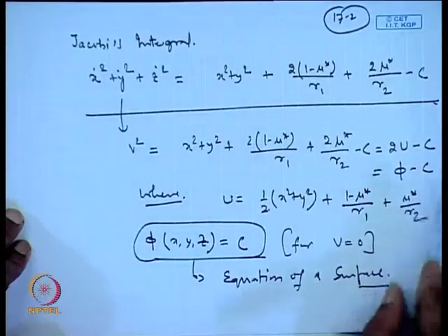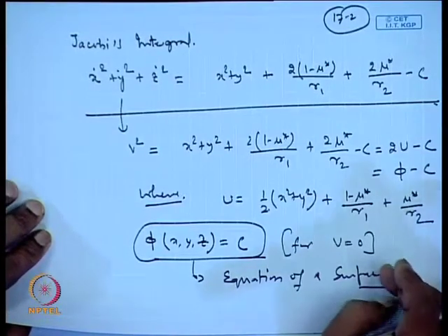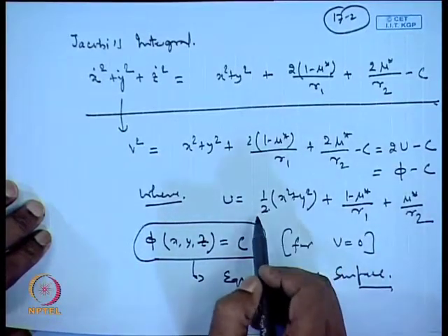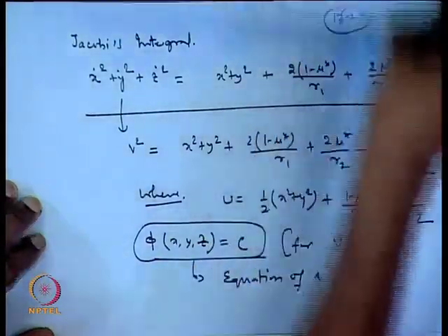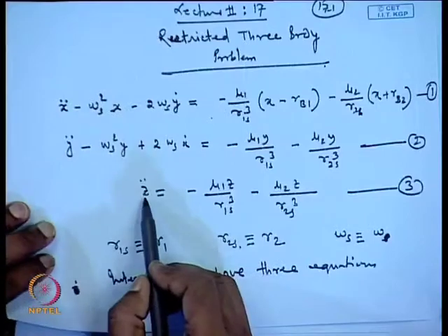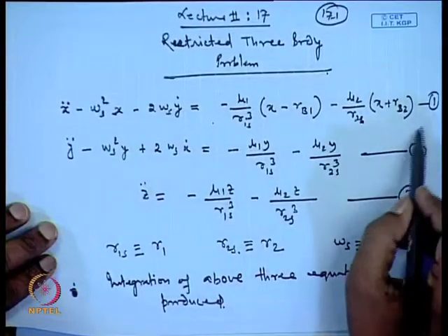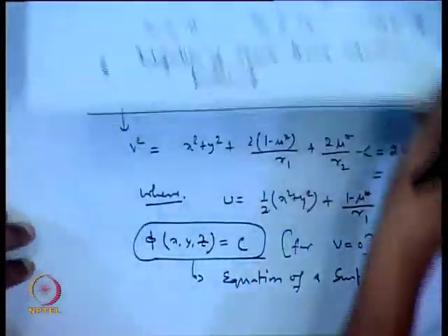What we were discussing about were the librational points, or the equilibrium points, which are also called the Lagrange points. They arise once we set x double dot, y double dot and z double dot equal to 0 and x dot, y dot, z dot equal to 0 and substitute into these equations, and the resulting equations provide us the librational points. So, we need to solve them. I also stated that the librational points are nothing but the double points.